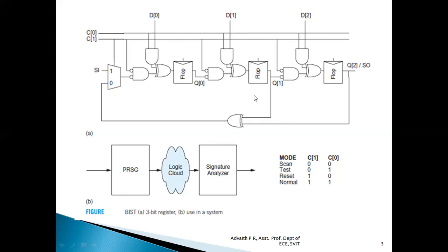In summary, built-in self-test is performed by first resetting the syndrome in the output register. Syndrome is nothing but fault. Then both the registers are placed in test mode to produce pseudo-random inputs and identify the syndrome. Finally, the fault is shifted out through the scan chain.